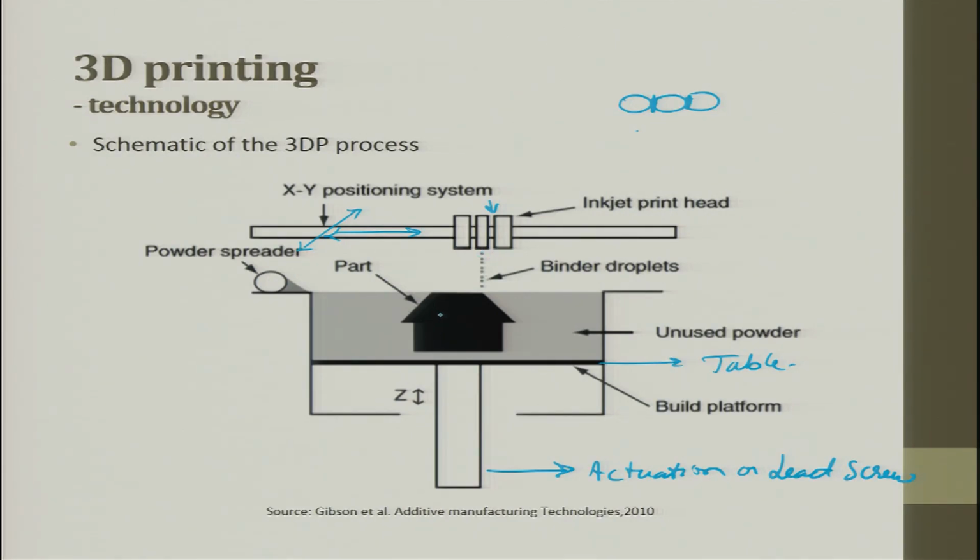After this, the part can be immersed inside of another polymer, varnish or something like that, so that the outer core layer is stiffened. Okay. So here the part need not have very high strength. It is only to give a form, shape by this process. Okay. After this, you can use this as a pattern for making a mold to a component, etc., etc.